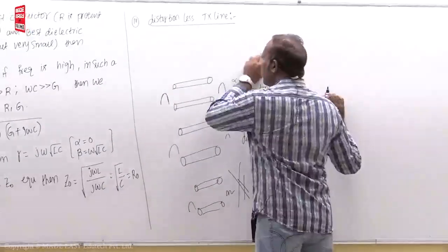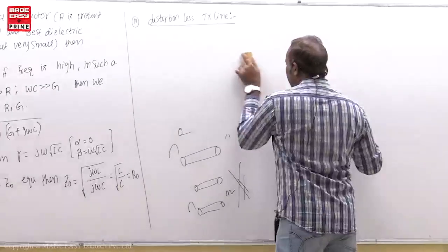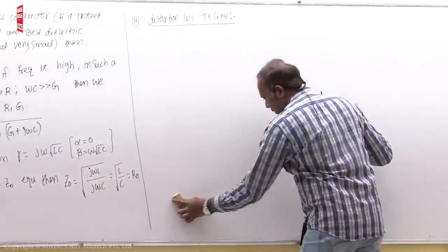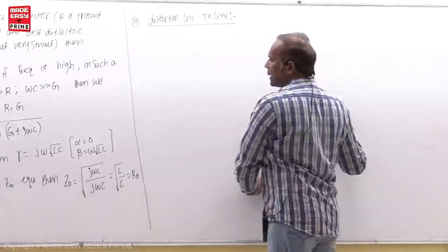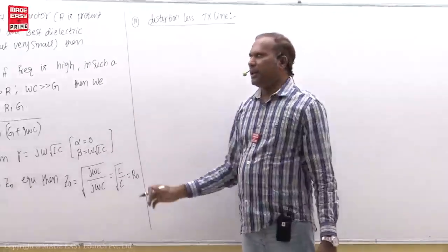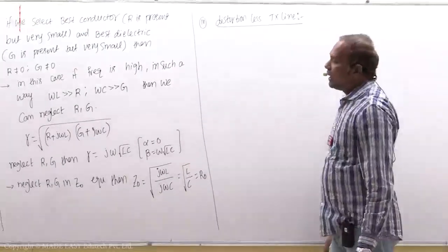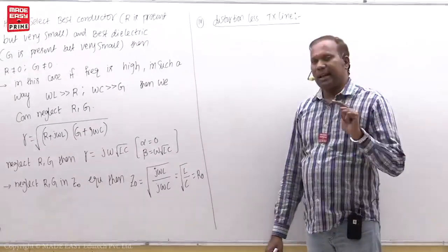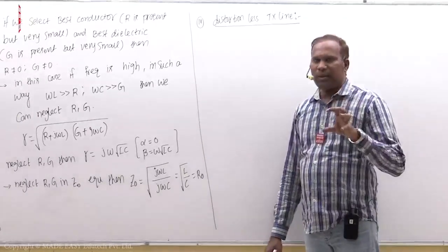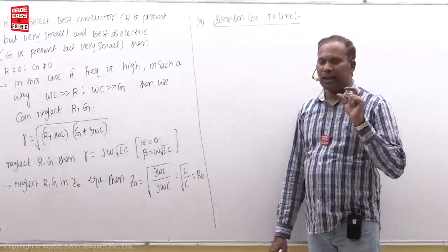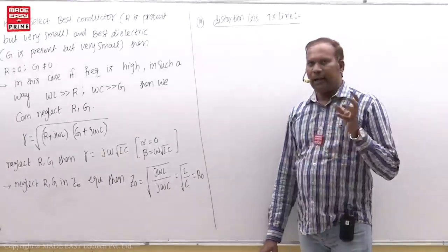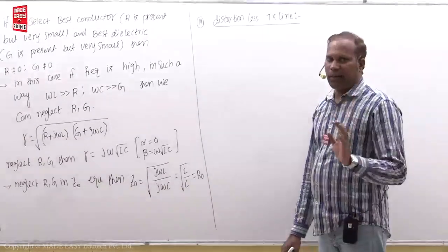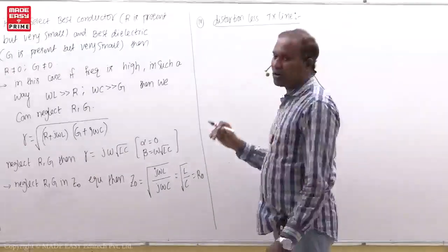So dear students, distortionless transmission line. Actually, in communication engineering, one definition is there. If any transmission structure, like a two-wire transmission line, a coaxial cable, etc., is to be distortionless, then the attenuation constant alpha of that transmission structure should be constant. That means alpha should be independent of frequency, and the phase shift constant beta must be a linear function of frequency. That is the definition. Actually, I am writing the definition here. That is also an objective question.